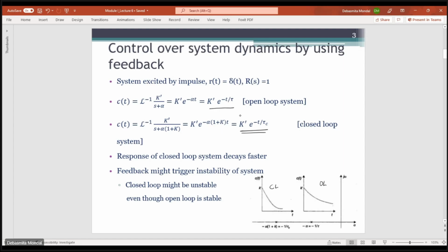For this closed loop system, if you write the expression for C(s) by N(s), again for R(s) equals 0, you get C(s) by N(s) equals GB(s) by 1 plus GA GB into H(s). If you compare the open loop and closed loop equations, you see that in the closed loop case, the output due to the noise, if noise is considered as the input, is much less when the feedback mechanism is in play.